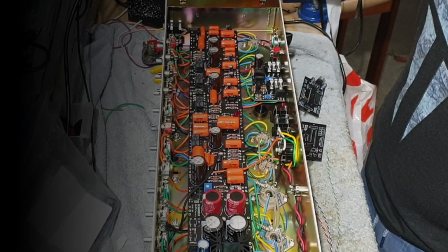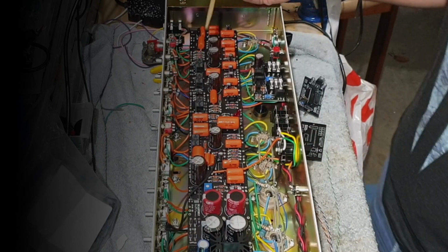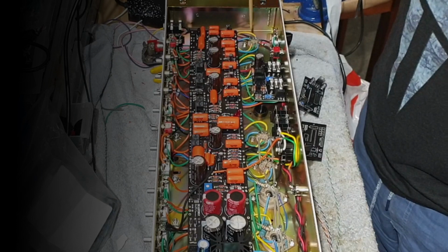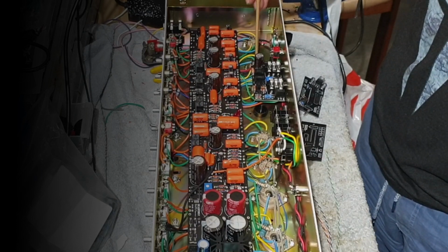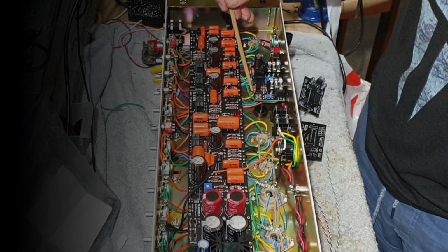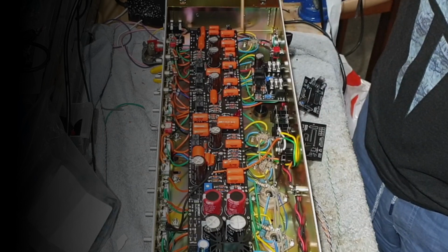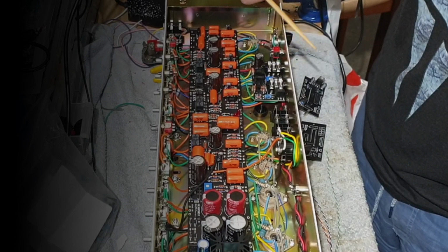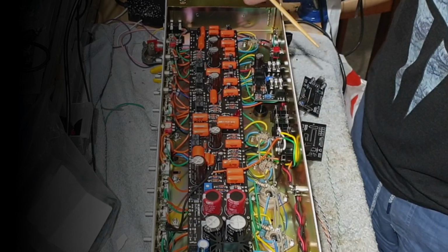Also, 12 volts is a good option if you've got a power transformer that can serve that up, because we're doing DC heaters on these first 3 preamp tubes. And you can see on my chassis here, this is drilled for 6 12AX7s. The MTL board uses 5, right? It doesn't use a tube loop.